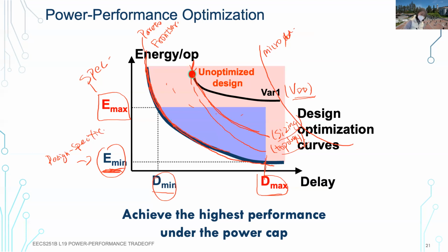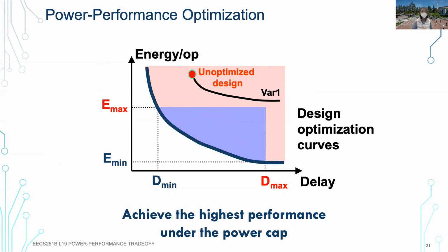So we show this frontier, but to actually get to this frontier, there are a lot of different design trade-offs that we consider. That's why, when you hear people talk about design space exploration, it's basically about how we get to this frontier, across all the different dots. We talk about all the different parameters like VDD, sizing, topology, and also microarchitecture. All of these can have interesting implications and will affect the shape of this frontier. So it's hardware dependent, circuit dependent, device dependent, and also microarchitecture dependent.